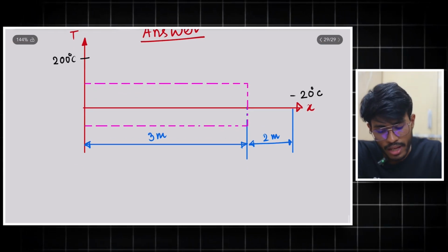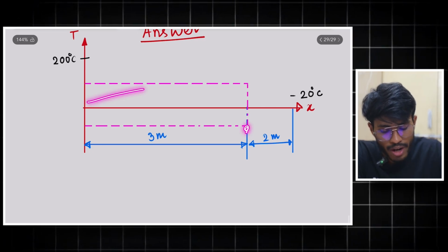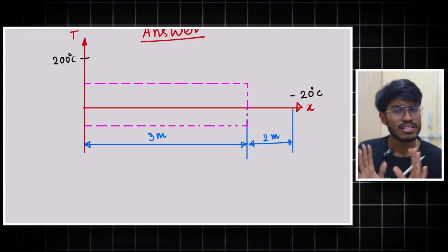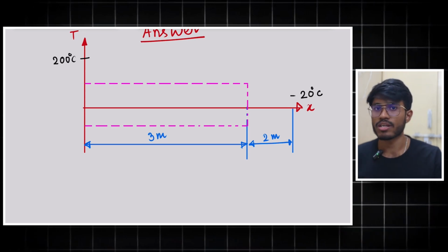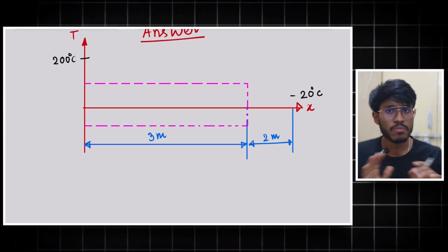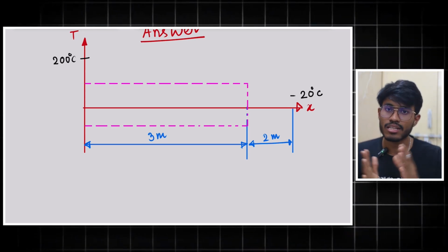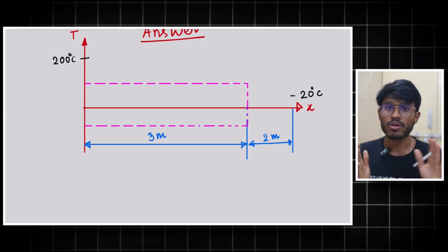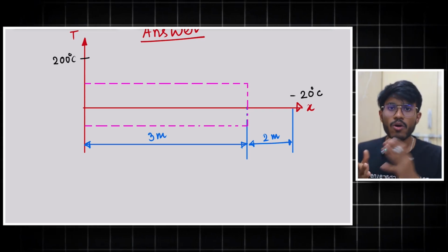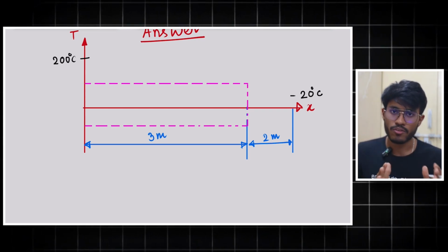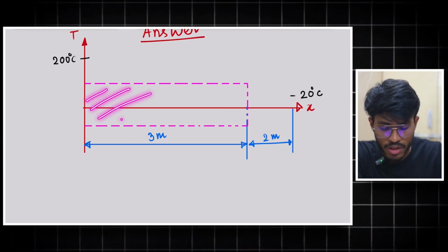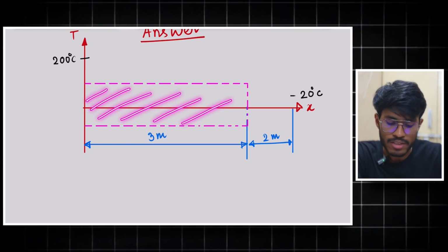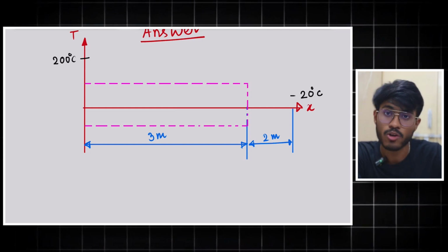Up to this point, I have conduction in solid. In solid, there cannot be any kind of convection. There can be radiation, but we are neglecting radiation in the solid medium. Generally, we don't have radiation in the solid medium; we have radiation in gas or liquid. So here, only 1D conduction, and we know that the area is constant.